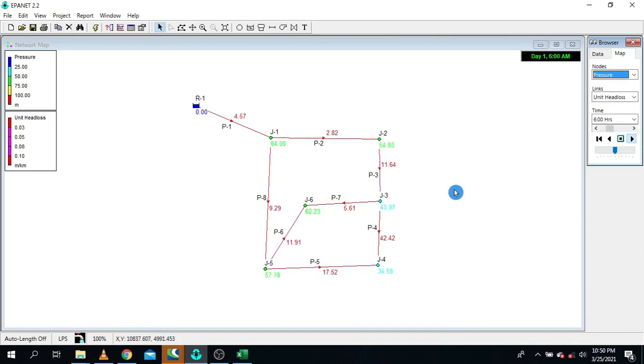But one thing here we need to notice, if we didn't change anything, possibly our system would not be able to withstand demand fluctuations within a day. So as engineers, I think it is very important to take this into account, and if possible, and if your system is expected to be consumed by a large community, it is very important to perform extended period simulations.